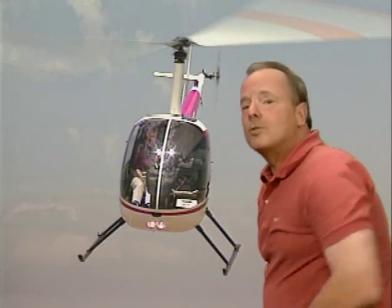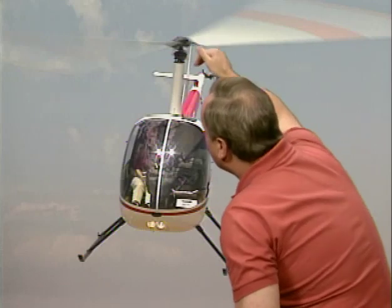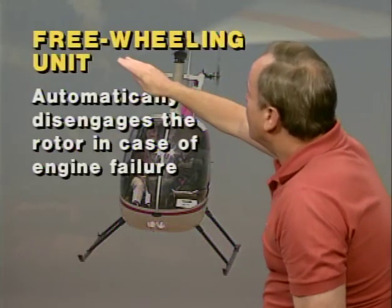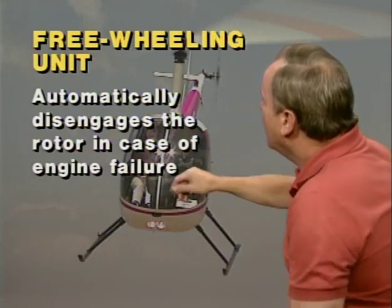In the event of an engine failure, it's very important to maintain rotor RPM, so you don't want the engine slowing it down, so therefore there is a solution. And that solution is called the freewheeling unit or freewheeling clutch, and it automatically disengages the rotor in case of engine failure.